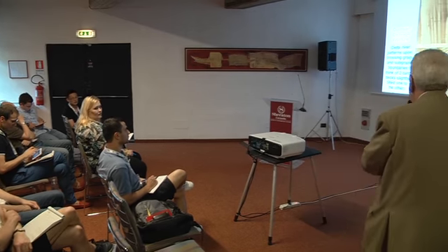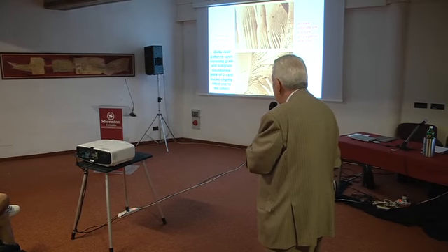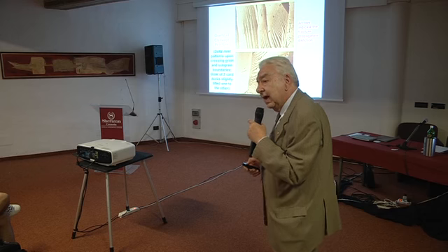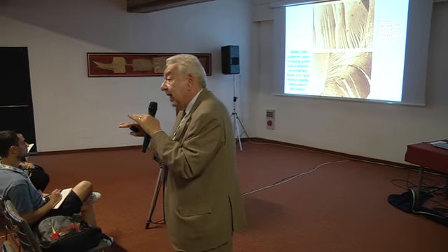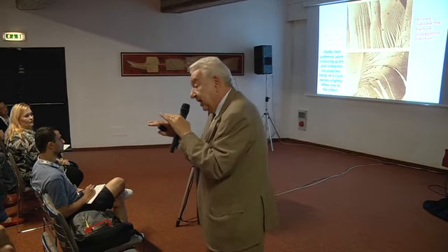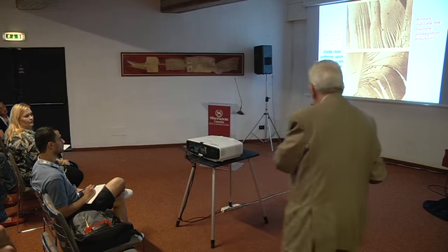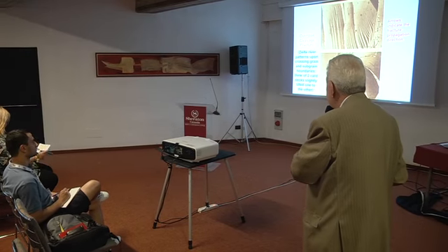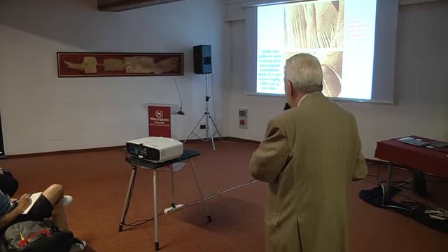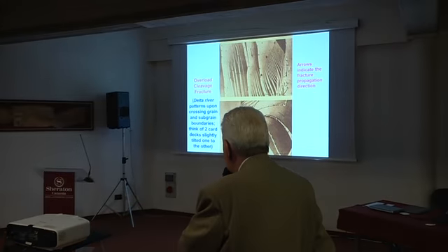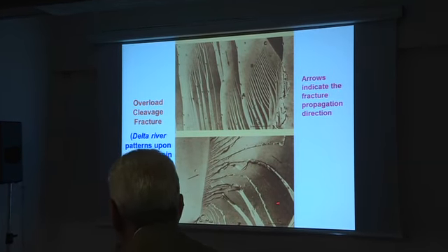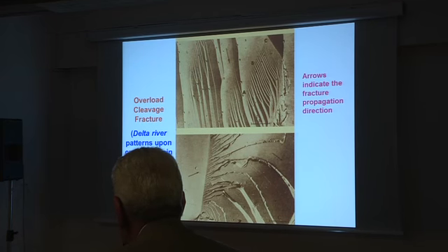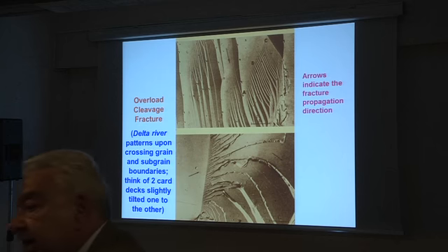Then nature tries to go to the least absorbed energy ever, and then as the fracture progresses from the boundary into the bulk of the other crystal, since each of these steps, which is a shear step between one cleavage plane and the other cleavage plane, is an energy absorbing mechanism, then nature tends to reduce these steps, taking the fracture into single larger facets, and the shear steps become larger, but each one absorbs less energy than the multiple ones that you see at the boundary, passing from one crystal to the other crystal.